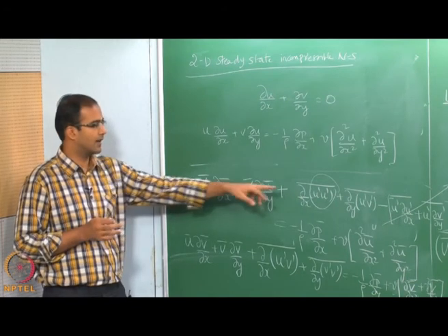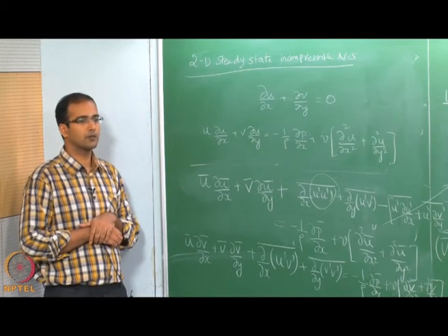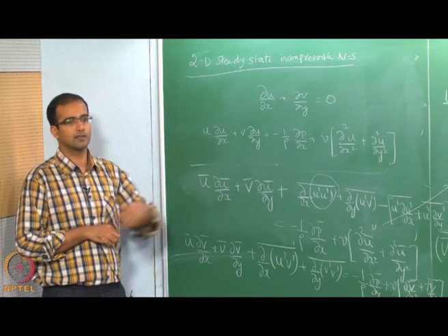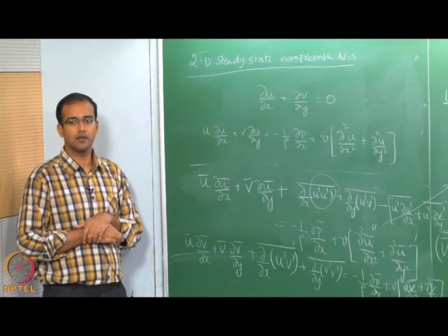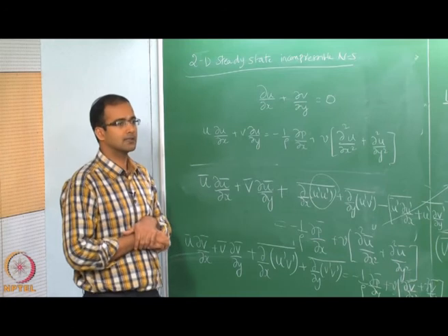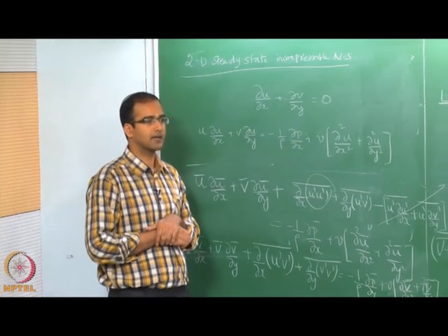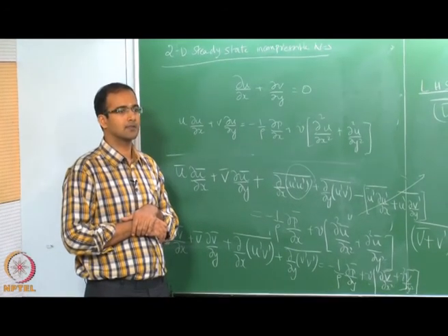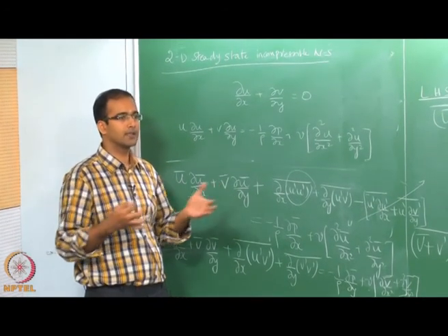Apart from that you also have u prime squared bar, u prime v prime bar and so on. These are now called turbulent stresses. Although the nature of these stresses originates from the advection term, they are named turbulent stresses just for the ease of grouping these together.